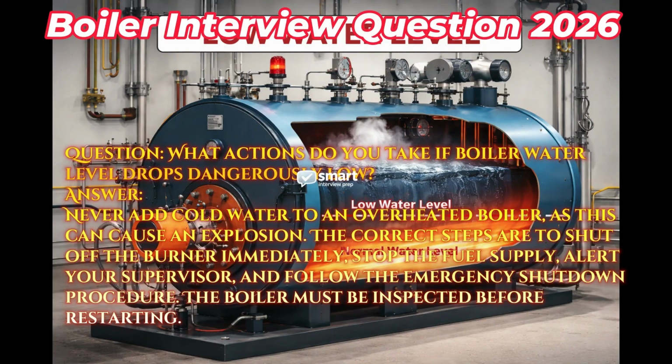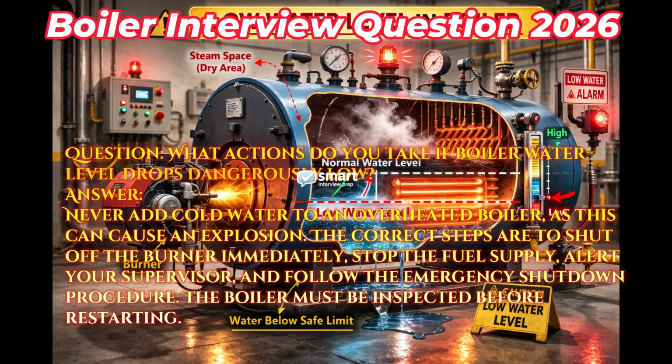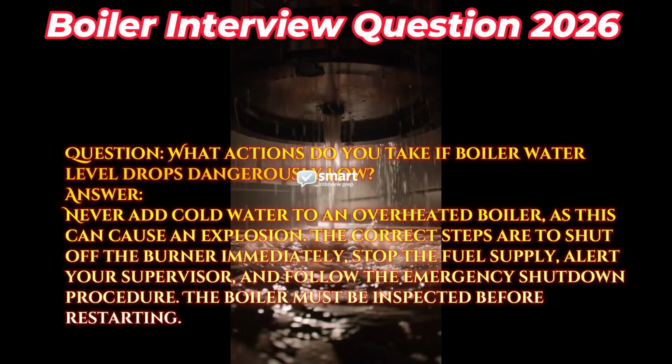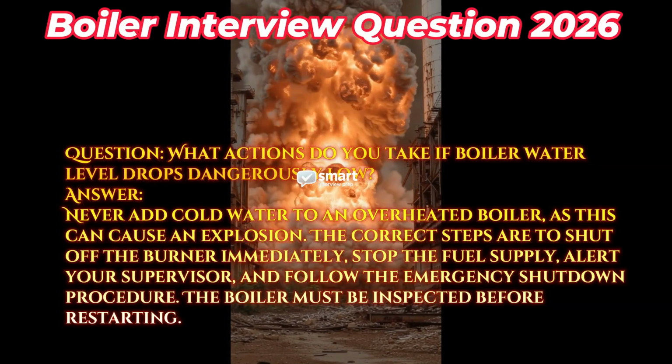Question: What actions do you take if boiler water level drops dangerously low? Answer: Never add cold water to an overheated boiler, as this can cause an explosion. The correct steps are to shut off the burner immediately, stop the fuel supply, alert your supervisor, and follow the emergency shutdown procedure. The boiler must be inspected before restarting.